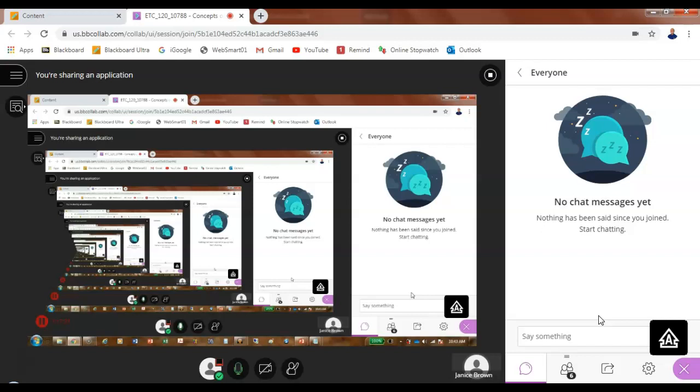The RMS. This is where I have to go to see your answers. So I'm back to the mirrored screen. We looked at the circuit, so y'all don't need the circuit anymore. It's a full wave. I'm using a 12.6 volt center tap transformer. It is a full wave center tap, unregulated, unfiltered circuit.